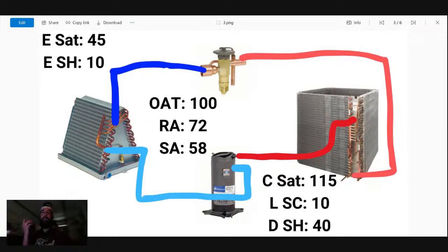We get up into the attic and we start looking at the air handler. In that process, we see the blower was set up on high speed. Whether it was recently moved, just whatever the case may be, it was set up on high speed on the blower. So the next call would be, well, let's lower that fan speed down.